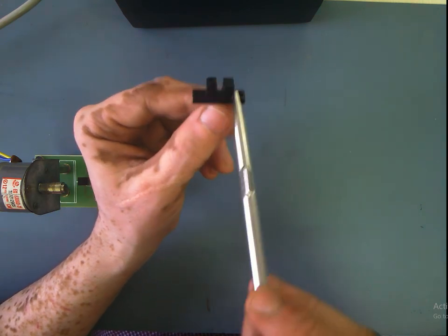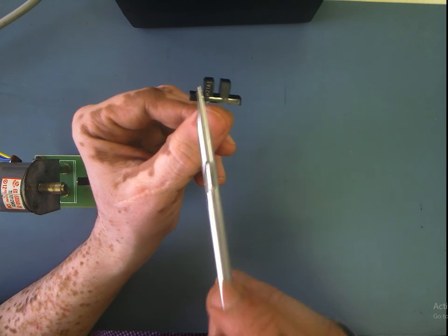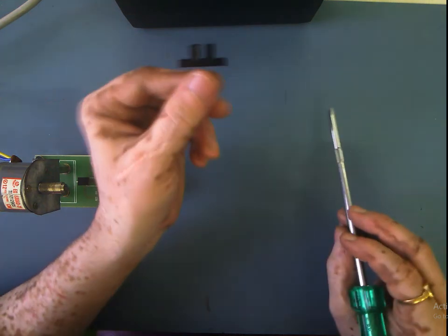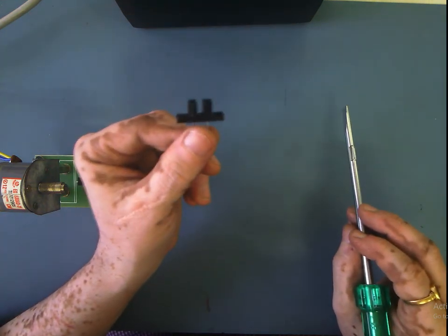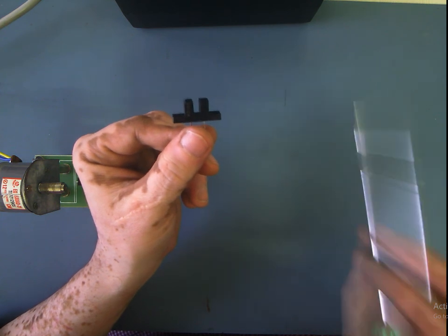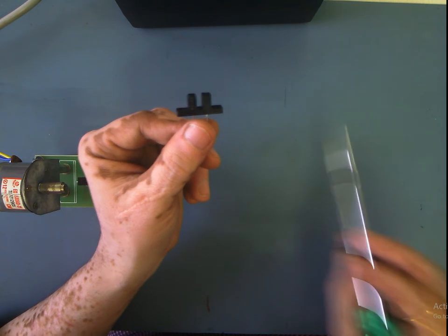When there is nothing in this slot, the signal of the diode will reach the phototransistor. So at the phototransistor base, we will have the IR signal. So the transistor will start conducting. Now consider the resistance and collector combination.